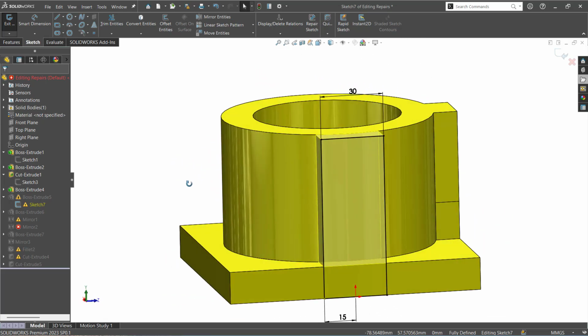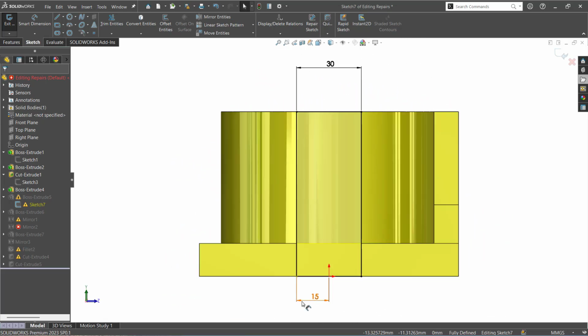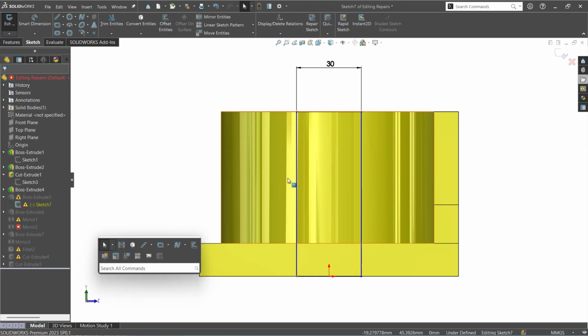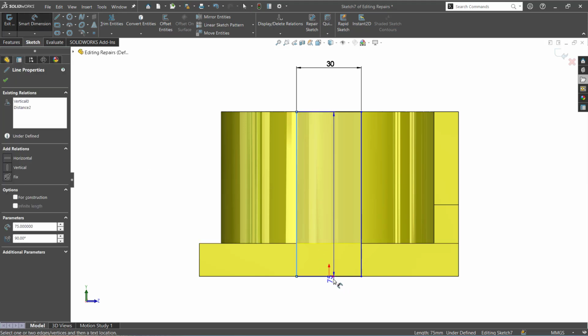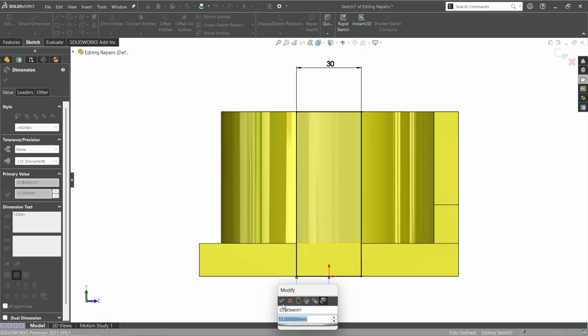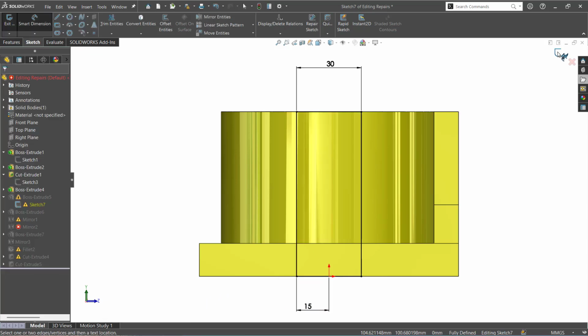The length. Okay. So here I selected the point. You could see that point is gray. Correct? So it shouldn't be gray. So what you do is you delete this dimension and assign it again from here to here. Okay. Yes.